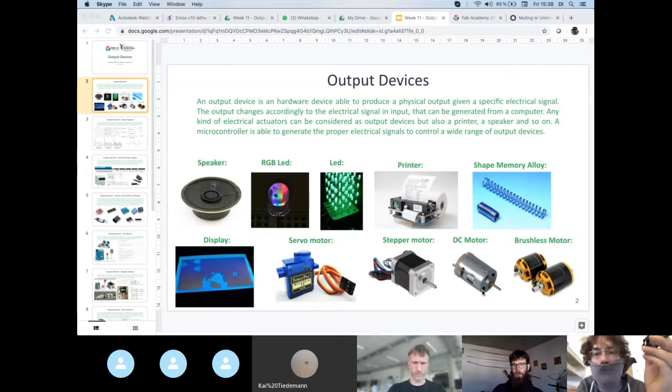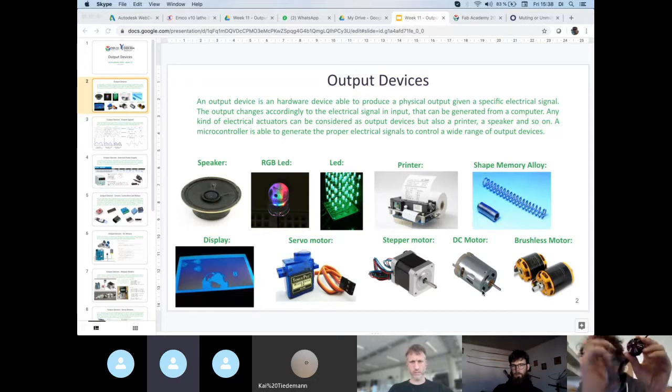So for my final project idea. It depends also on the construction of the motor itself, because some motors are made to express the maximum torque at a certain rotation speed. Some other motors can have some torque at a really low speed, or from stop, let's say. So with the ones from drones, for example, I can almost block them by hand when they start rotating, because they're made to have the maximum torque at the speed of the propeller, you know.